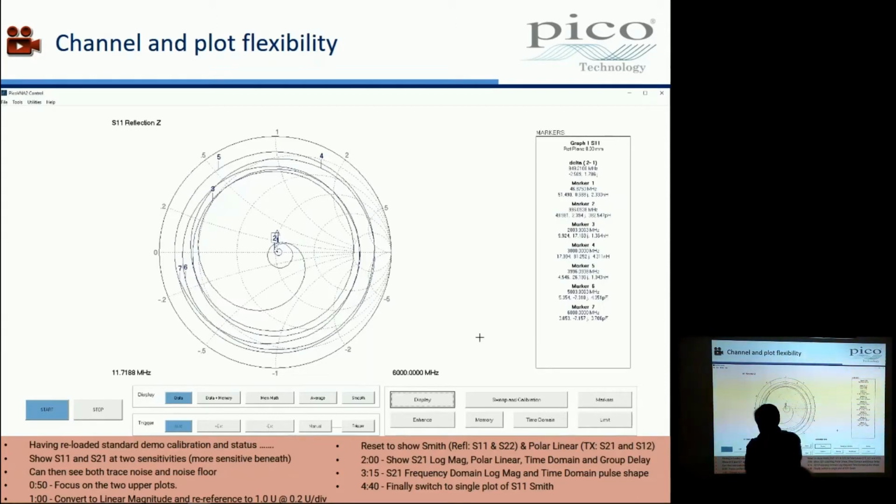We saw a polar plot. We saw a polar plot of S21. We can probably get our heads around the transmission characteristic having a gain vector, a set of complex numbers that represent the gain of the system, the through gain of the system. Well, this is a polar plot of S22. It's just the same plot as we saw on S21. It's just a polar plot of the real and imaginary components in the numbers that are coming off the processing of the received waves.